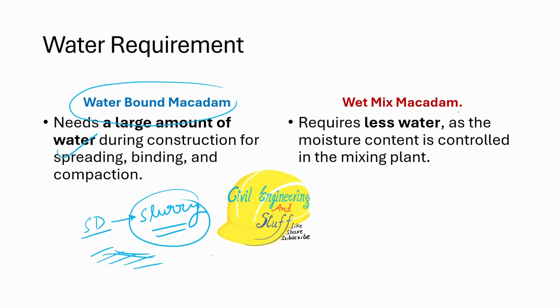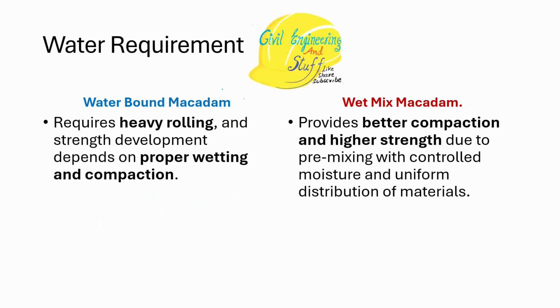While in wet mix macadam, we have full quality control, right? We specify what the OMC value needs to be and how the work needs to be executed. So there is relatively less water wastage and more quality control in wet mix macadam than in WBM.